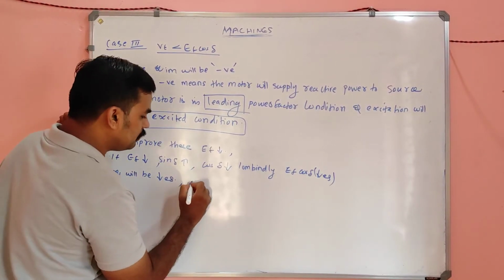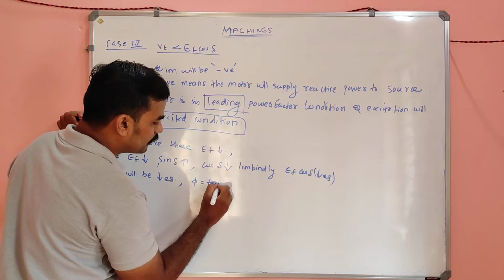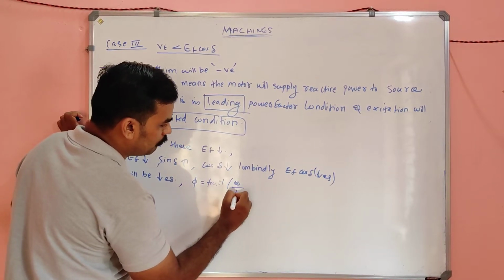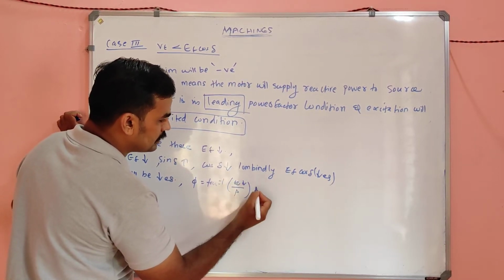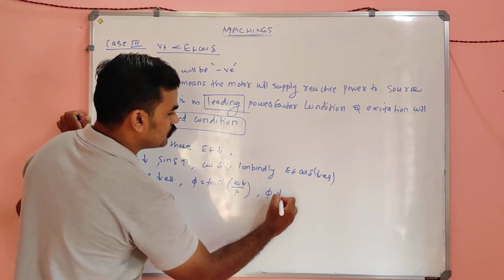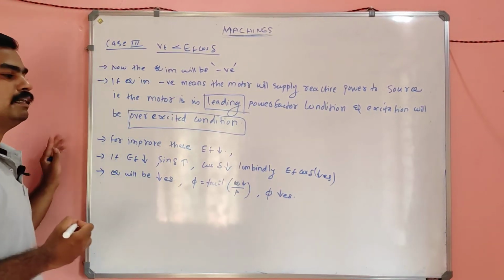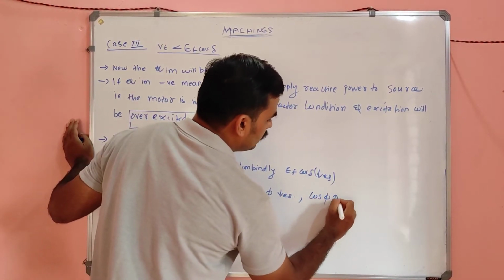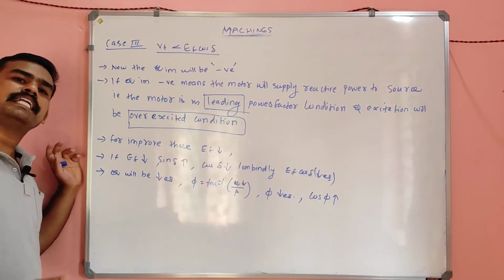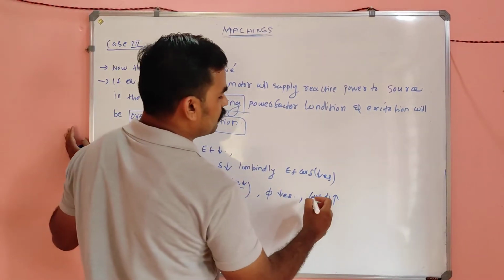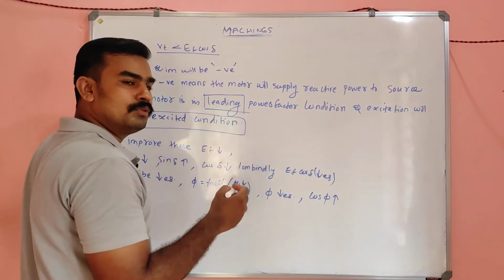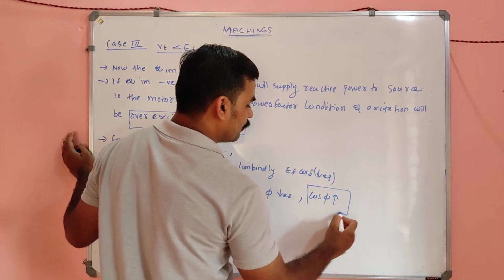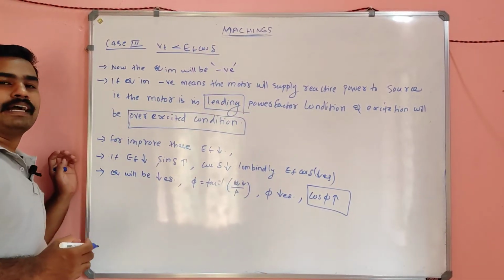If Q decreases, phi, which is tan inverse Q by P, also decreases. If phi decreases, my dear, cos phi increases. So cos phi increases from the leading to unity. The cos phi now finally what, my dear?